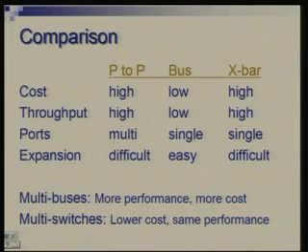On the other hand, instead of having a monolithic single crossbar switch which connects everyone, you could also divide into a few smaller crossbar switches, and that would be meaningful if everyone need not talk to everyone. For example, in our situation, we don't necessarily want one peripheral device to talk to another peripheral device. So that complete crossbar capability is not required.